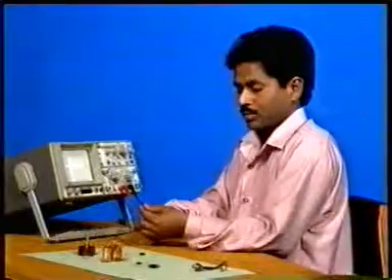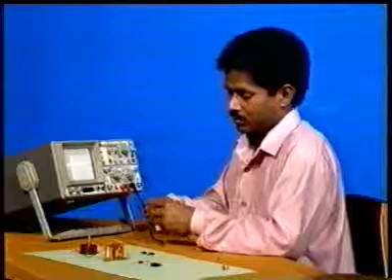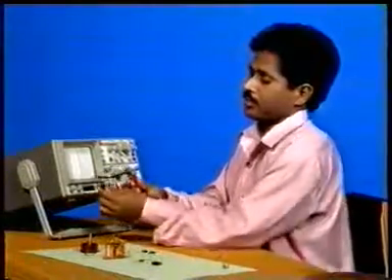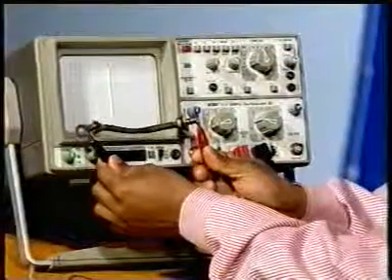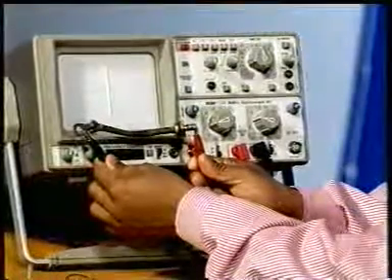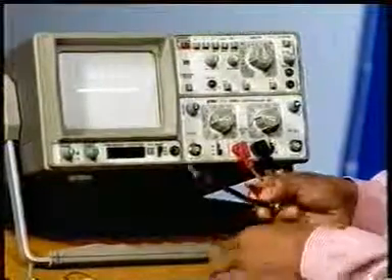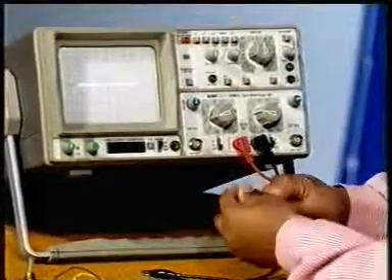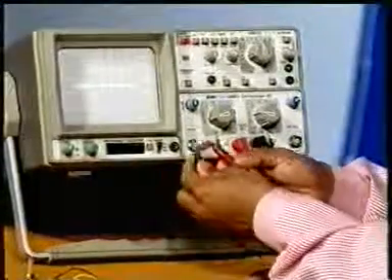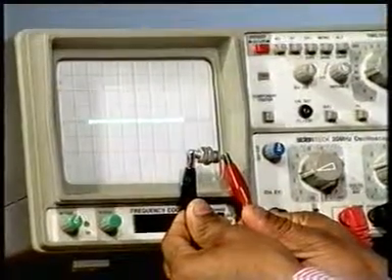Now you can check some of the damaged components also. You see, incidentally both these components are power diodes. Yes, sir. They are power diodes. Now you are getting a vertical line. What does it mean? This shows that this particular device is short. Now let us check another one. The second one, that is also a power diode. Yes, sir. And in this case you are getting a horizontal line. What does it mean? It means that the device is open.